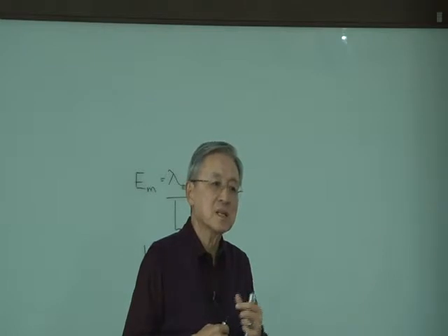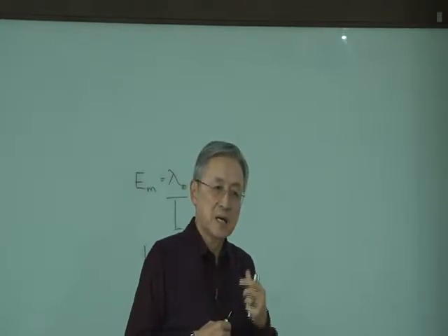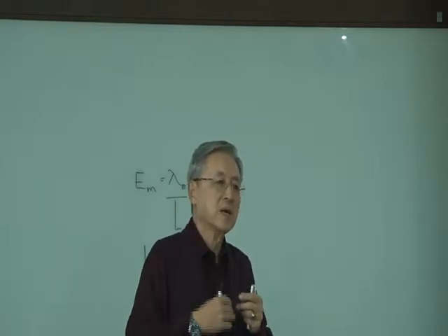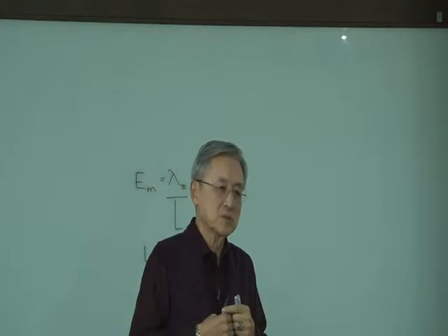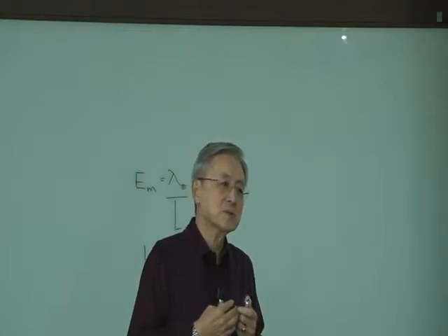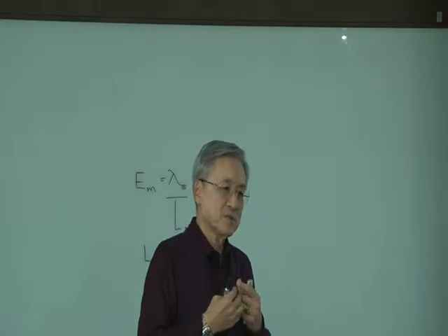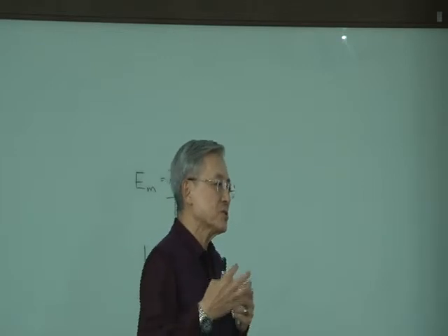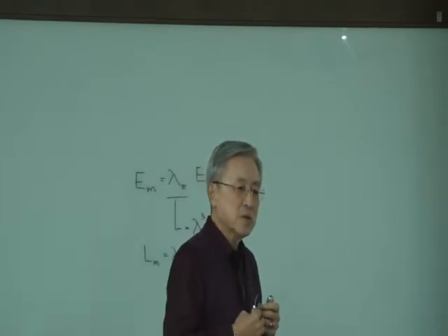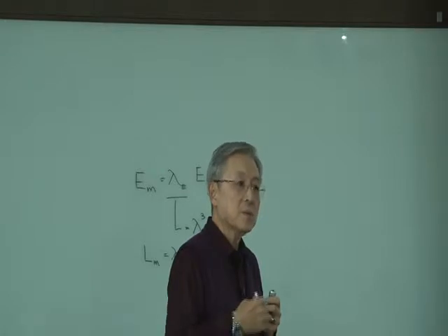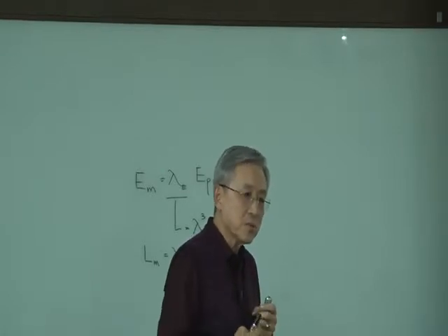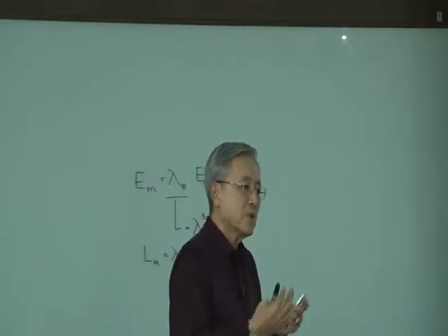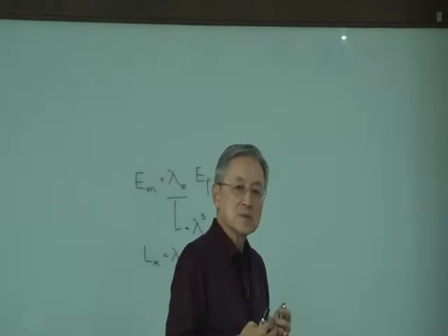So if it's a nonlinear phenomenon, you cannot really use Hopkinson's scaling for quantities such as viscous damping, structural damping, or energy dissipation. But of course, as a good approximation with understanding, you can use it.